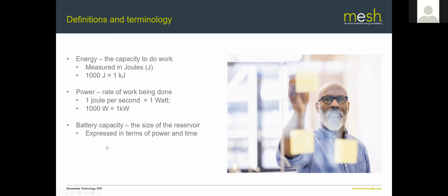If you take power, which is joules per second, which already has time on the bottom of the equation, and then you multiply it by time, the times cancel out, and you end up back with a unit of energy, but it's expressed in terms of kilowatt hours. If you had a 1 kilowatt load and you ran it for 1 hour, how much energy would it use? The answer is 3.6 million joules.